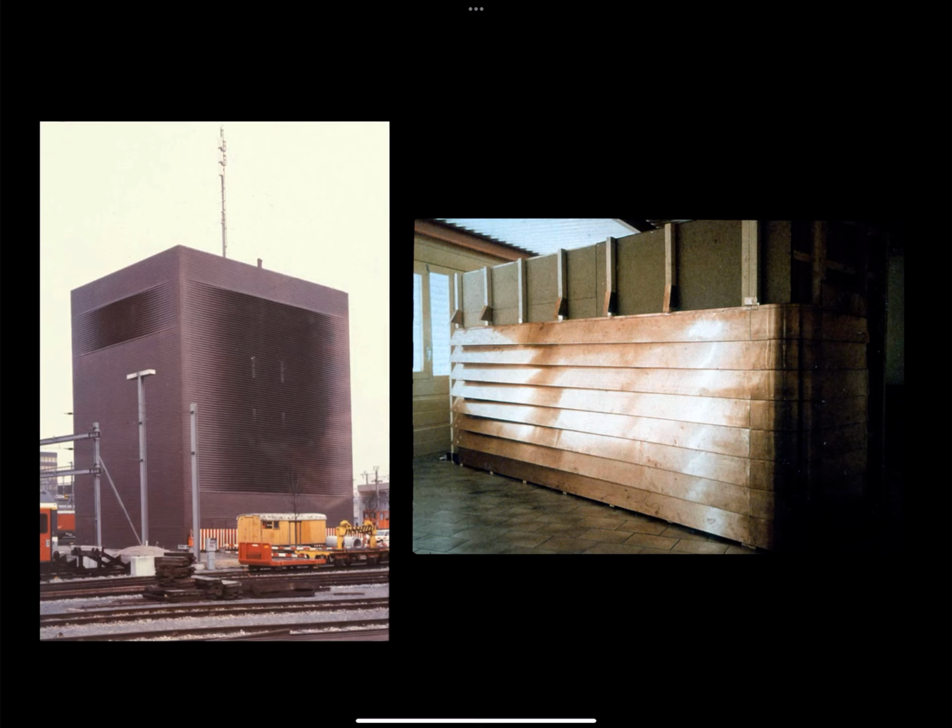And the backup wall here is just a very traditional solid wall with a stucco finish. And then there's about a 2 foot wide airspace or cavity. And then the outer skin is this banded copper cladding that you see here. So what you see on the right is a mock-up that they built to test this system. This is not a standard manufactured system. It's a system that they designed especially for this building.